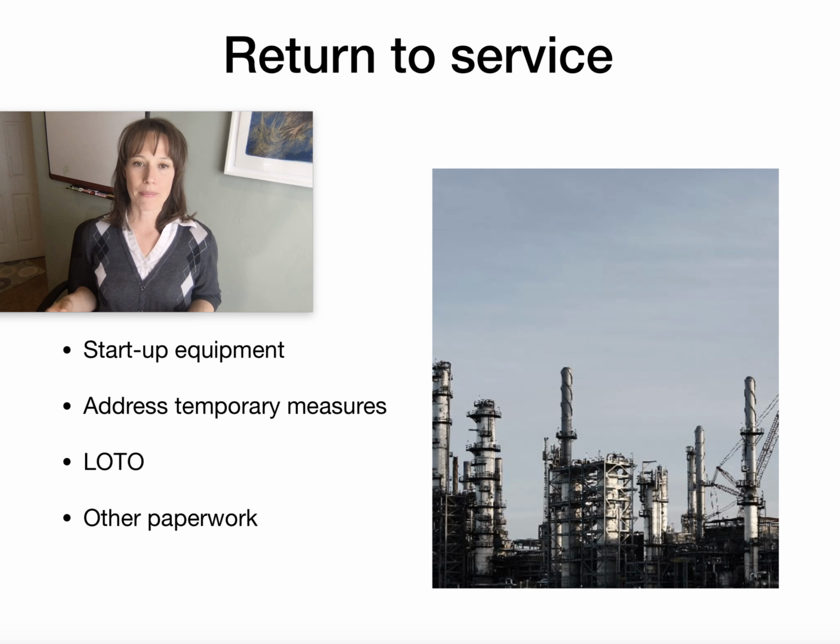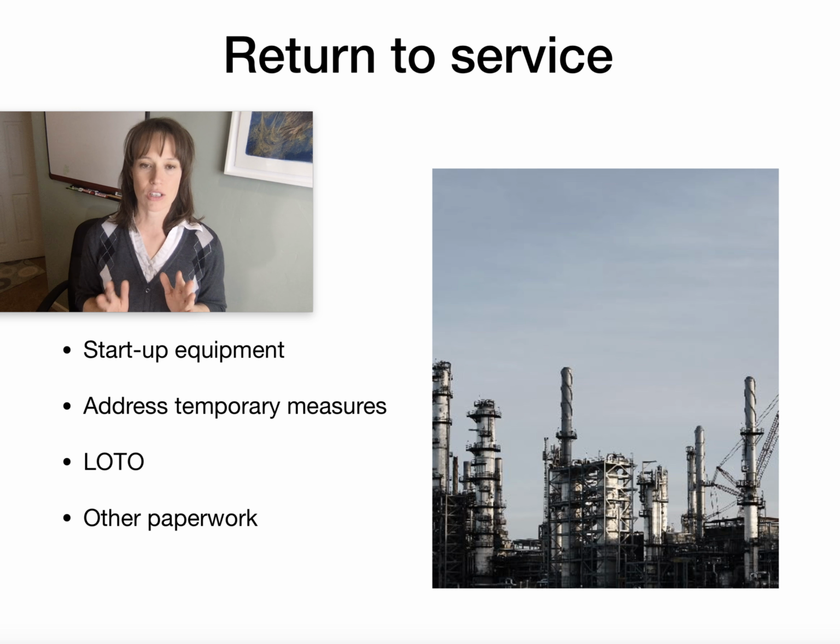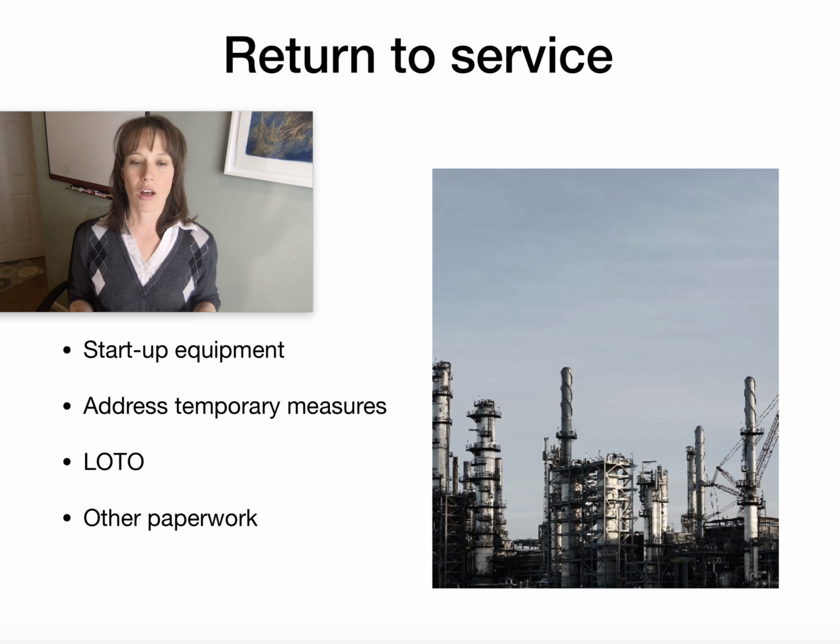If there was a bypass or valves opened, valves closed, anything that you've done temporarily to the system, you need to address those, to undo the bypass, make sure it's going back through the main line, do all that.